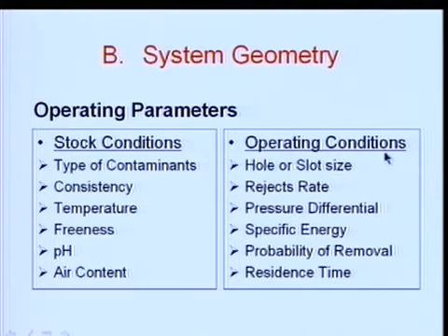Then operating conditions. If you have screens, what are the hole or slot sizes, or in washing, what's the mesh size, reject rates in each stage, pressure differential, what is the pressure difference between feed and accepts, specific energy, how much energy is being used, probability of removal. Let's talk about that a little bit. We've already probably talked about that in your screens and cleaners.